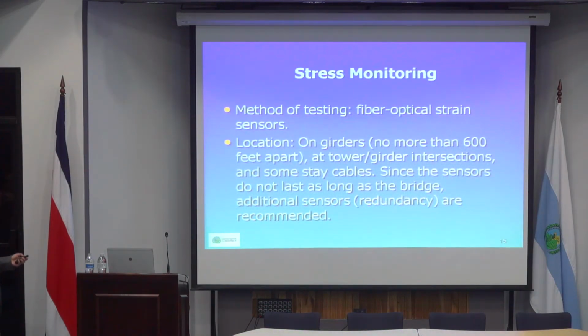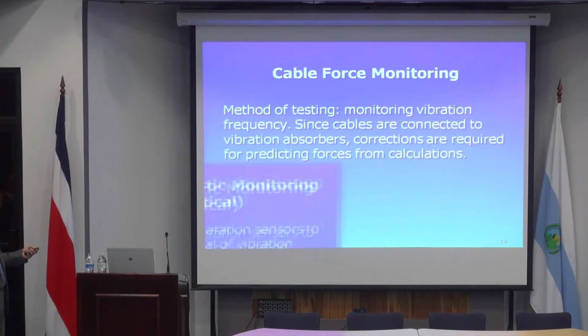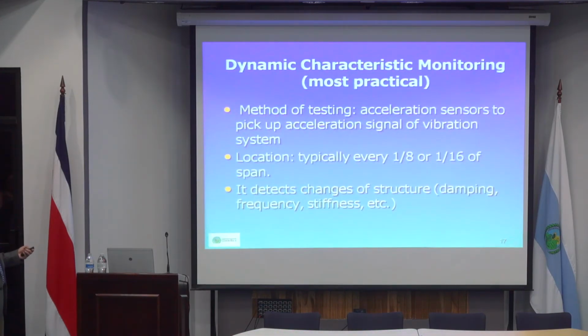And the stress monitoring, cable force, and different things can be modeled. Again, the dynamic, even for a suspension cable, for example, has its own vibration frequencies. So if we imagine one day some cable is broken inside, then the vibration frequency will change.